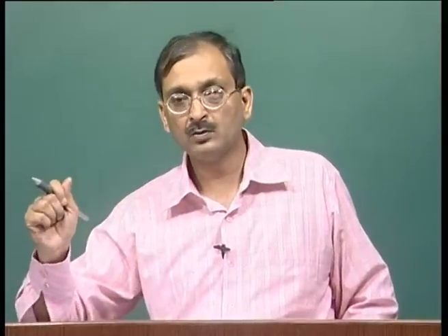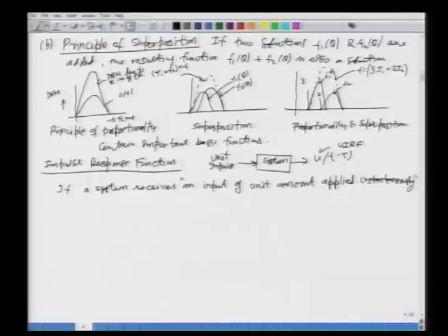instantaneously. All right. So, you dump 1 centimeter of rainfall instantaneously on a catchment, or you apply a force of unit amount to a system. Okay. What will be the response? That is called the unit impulse response function. All right. So, let me complete this. In the brackets, I am going to say a unit impulse for this at time tau.